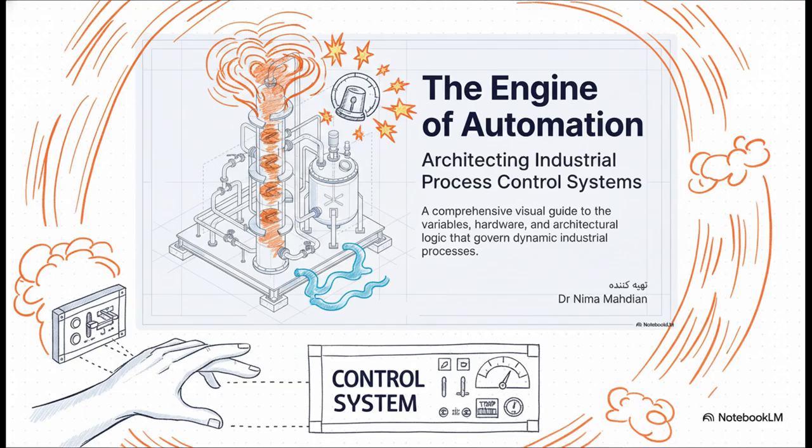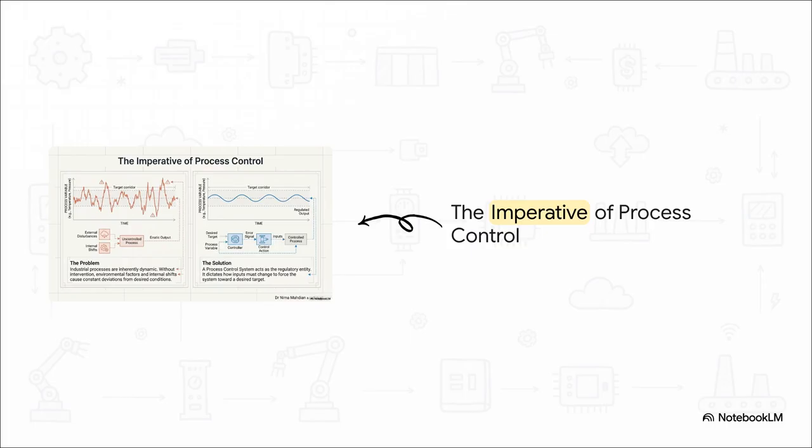And that right there is exactly why control engineers are so essential. We have to tame this machine. Look at what happens without us. An uncontrolled process, which you can see as that erratic, wild red line, just violently crashes outside of our safe target corridor. Why? Because of external disturbances, like maybe a sudden freezing rainstorm outside, or internal shifts. But when we add a controller, that smooth blue line, the system constantly calculates the error signal. That's just the difference between where we are right now and our desired target. It then takes immediate action to gently guide that temperature back to safety. It keeps everything smooth, stable, and safe.